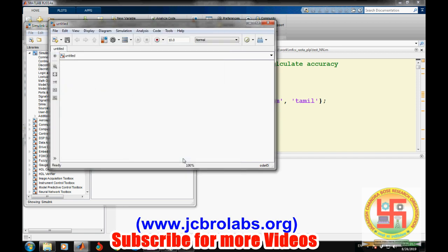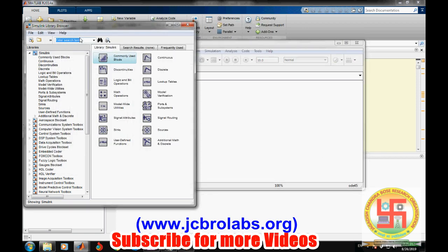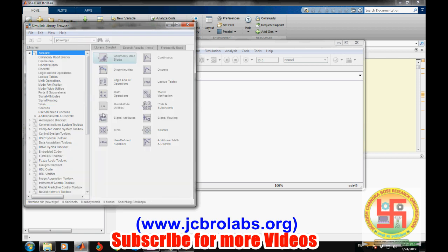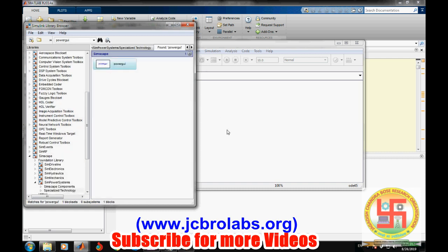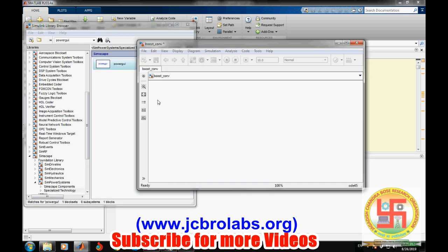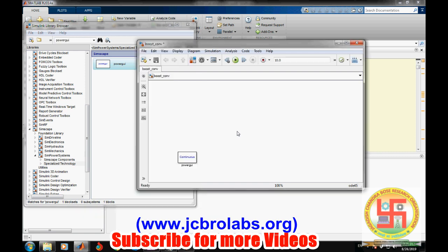So let's search the requirement. First of all, we'll need the power GUI. This power GUI is required to simulate the power system objects. You have to be very careful, like Simscape objects and SimPowerSystems objects, they are not interconnected. If you are selecting the power system objects, then all objects must be of power system only.